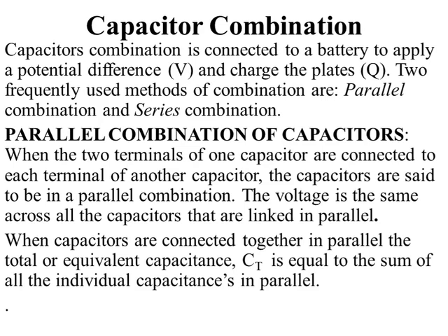Take for instance, you have a circuit diagram having capacitances C1, C2 and C3, and you have to get the equivalent capacitance. In this instance, your CT, which is the total or equivalent capacitance, you just have to sum those three capacitances together, which will be C1 plus C2 plus C3. So for parallel combination of capacitors, your equivalent capacitance is just the sum total of all the capacitances you have. This is different from what we did for the parallel combination of resistors.